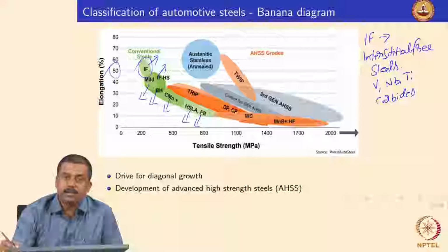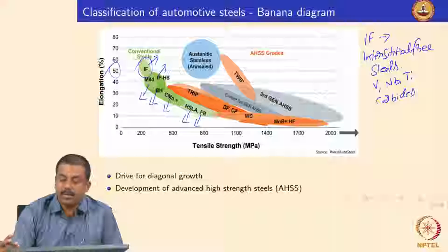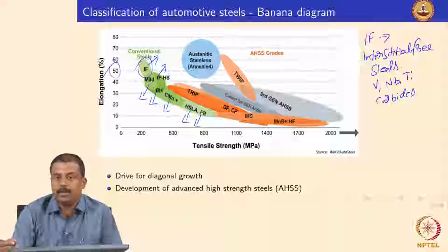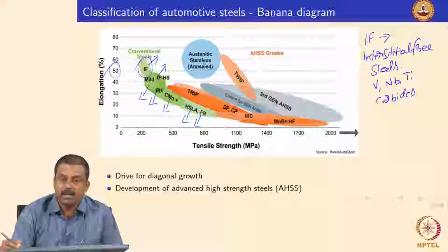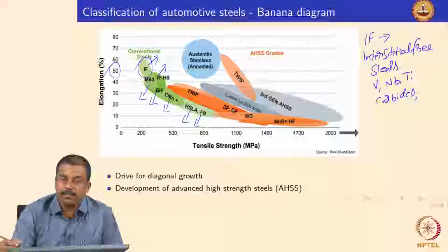By forming carbides, we deplete the iron matrix of interstitial atoms. The carbon is taken out of the interstitial positions to form vanadium carbide, niobium carbide and titanium carbide. Because of this carbide formation, we now have a pure ferrite matrix, and because of the pure ferritic microstructure, these steels have excellent ductility.